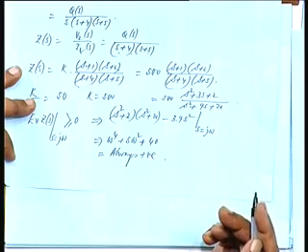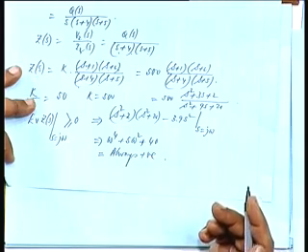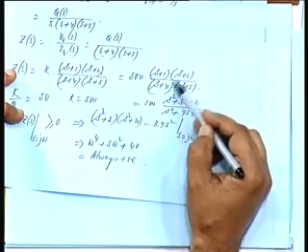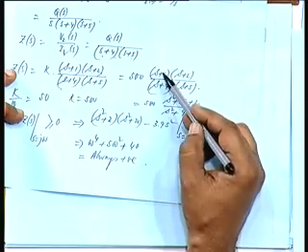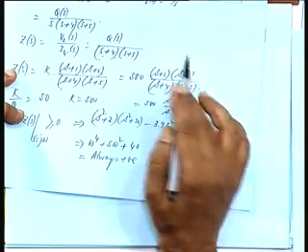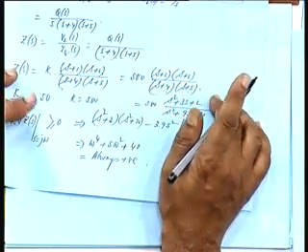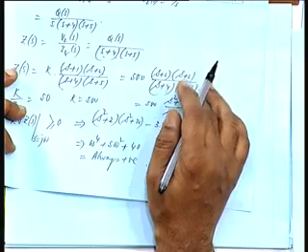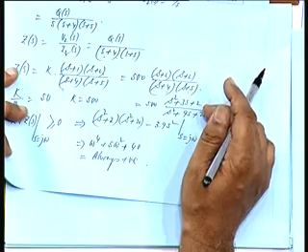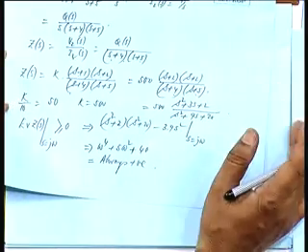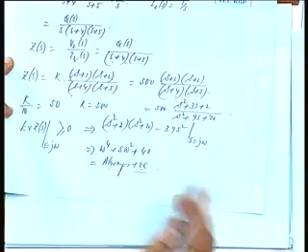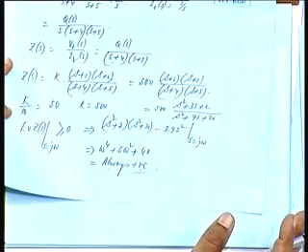So, it is a positive real function. Can you realize it by RL or RC? No, because the poles and zeros are not interlacing, zero zero pole pole, they are coming in this order. So, it will not be possible to realize this by RL or RC. We will see later on how this can be realized by RLC, that will be taken up later, but we know it can be realized because this is always positive. Is that okay?